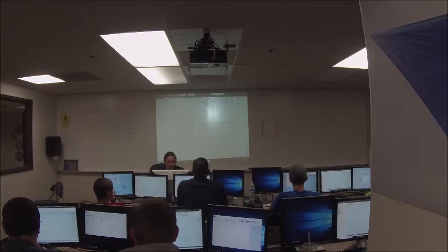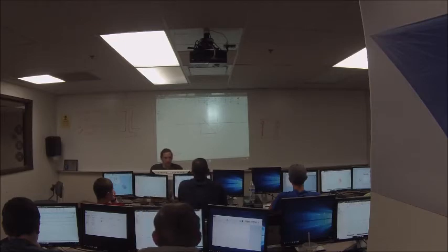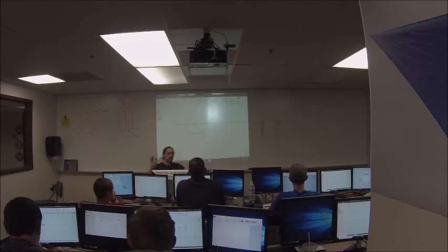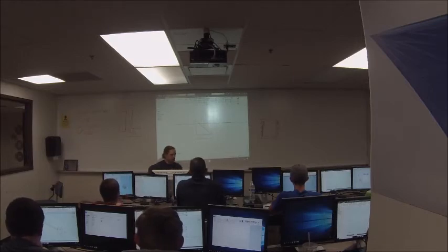Okay. I can dimension this triangle. Right, this triangle is fully constrained, right? This triangle can't change shape, it can't change size, but I can still click and drag it around. I can still move this triangle around, which is bad. I shouldn't be able to do that. So I need to attach it to the origin point somehow, so that it stays in place.